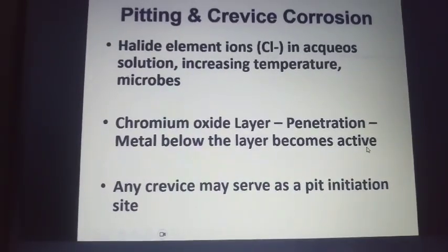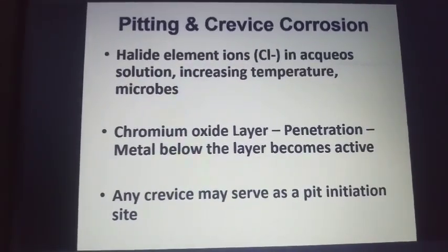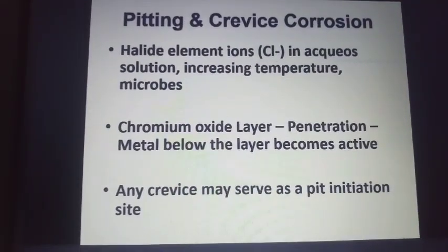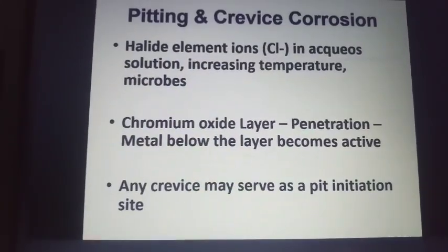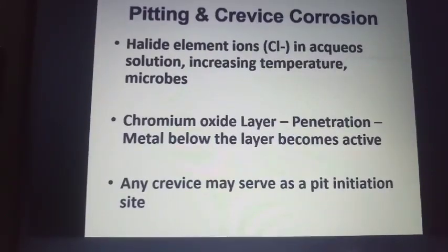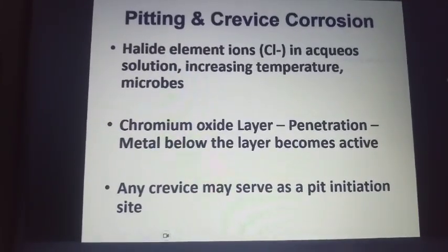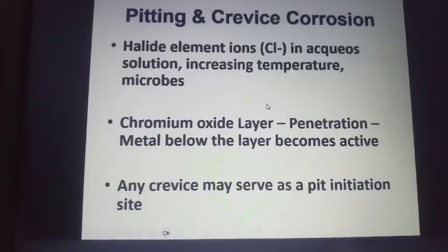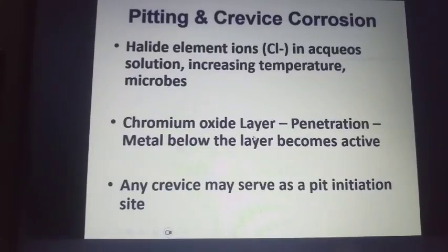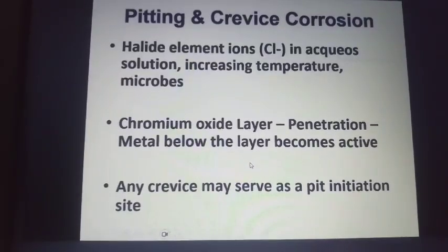So now in any stainless steel, the corrosion resistance is because of the chromium oxide. We increase chromium, about 12% or 18% in austenitic stainless steel. That forms a very thin, nanometer level chromium oxide layer. Okay, that chromium oxide basically gives the corrosion resistance. Now the problem is when you have chloride, it punctures the chromium oxide layer, the protection layer or the passivating layer. Then it goes below that layer and attacks the base material.